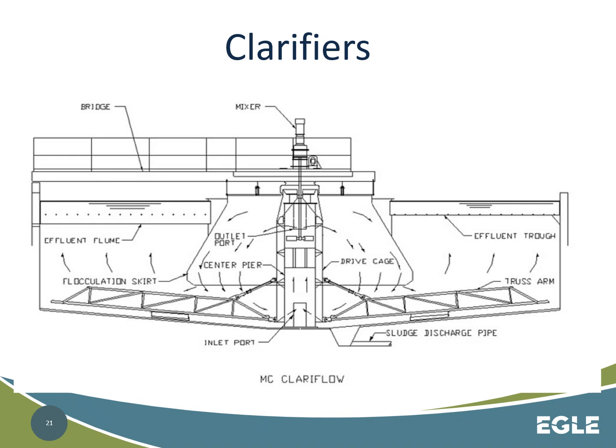Water flows up through the center mix zone, down through the slower mixing zone or flocculation zone, then flows underneath the skirt and enters the sludge blanket at the bottom of the clarifier. Flow velocity is reduced as water travels upwards, causing more and more material to precipitate and settle out. There is also a sludge blow-off line that helps control the size of the sludge blanket. Some of that sludge is usually recycled back into the process to seed the reactions.